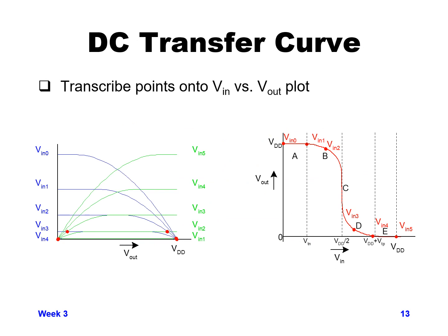So now instead of just plotting this at discrete Vn 1, 2, 3, 4, 5, if we actually swept our input voltage at every voltage between 0 and 5 volts, we would get something that looks like the graph on the right hand side there, where you can see at Vn 0, 1, and 2, we've got a curve that stays pretty close to a Vout of VDD.